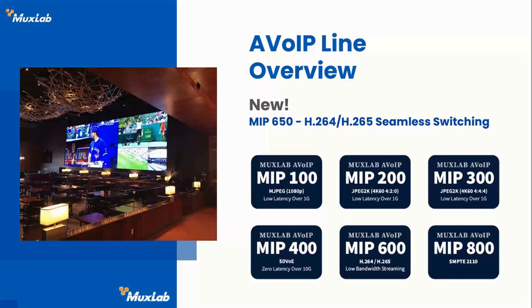It's a protocol that was designed by the industry for the broadcast industry. This category of products supports uncompressed transmission. So signals are not compressed. So we're running over a 10 gig or a 25 gig network, depending on the resolution of the product. And we have products in this category that go from 1080p up to 4K 60, which in the SDI world is called 3G SDI, all the way up to 12G SDI.